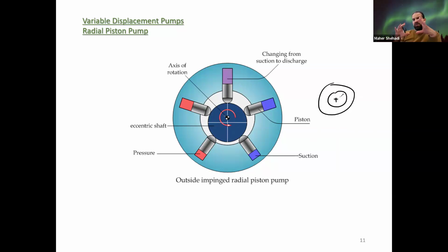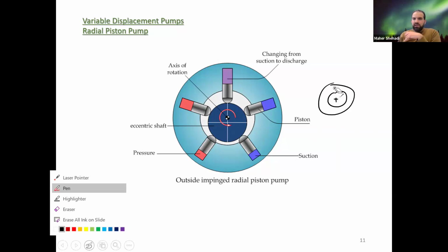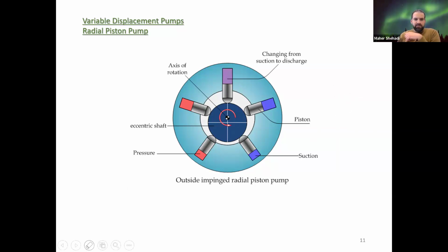And that's actually how we can control how much we can change that pressurization, because the more you move it, the smaller the chamber here at the outlet, so it would be pressurized more. And the textbook, for the next one, the vane pump, does show you how you can adjust it, because the vane pump is very similar to this type.